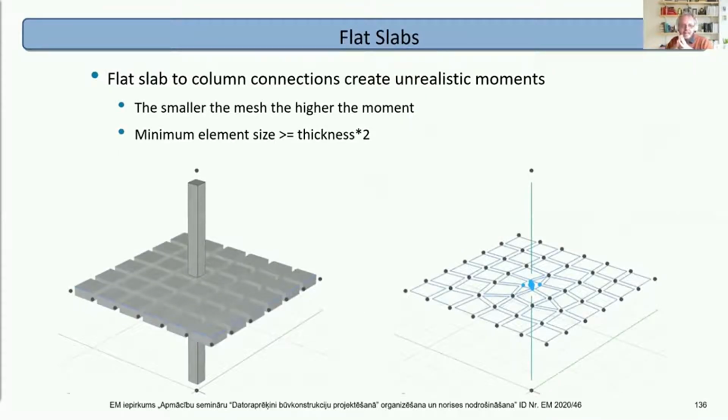Other things, flat slabs. Sometimes called flat plates in some countries. At the point where the slabs and the columns connect, you can get some very unrealistic moments. It depends on the element size, and the smaller the element size, the larger the moments. What we have here at the column slab connection is a singularity. So about metaphors, we have a metaphor of a one-dimensional element, a metaphor of a two-dimensional element, but at the connection it's really three-dimensional. The metaphor breaks down.